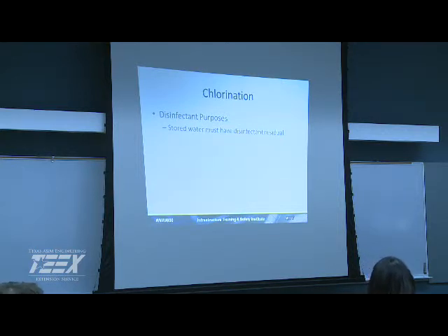A lot of people go down to the local pool supply and buy calcium hypochlorite, which is your powder, and it can be in tablet form. But the ones for swimming pools have a lot of other things in there that you don't want in your water, biocides and algaecides and things like that. So we're talking about NSF approved. As long as it's NSF approved, it's safe to be in your drinking water. And that's real important.